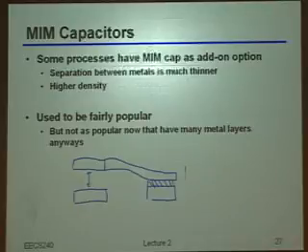And you'll typically use some kind of high K dielectric in between them. Or if not, just bring them closer to get a higher capacitance density. With a thinner oxide or thinner dielectric, perhaps a higher dielectric constant, you can get a higher capacitance per unit area, and also typically better parasitic characteristics.